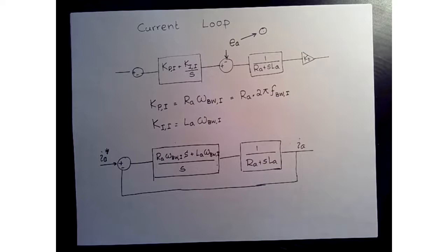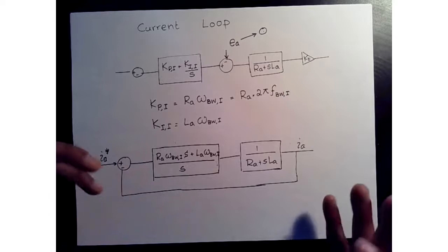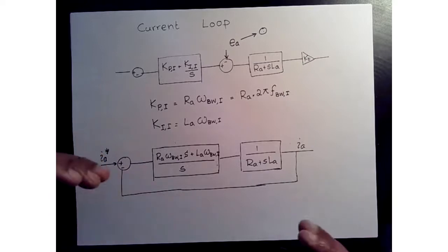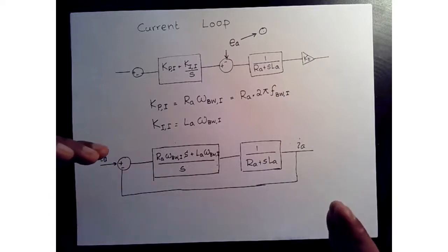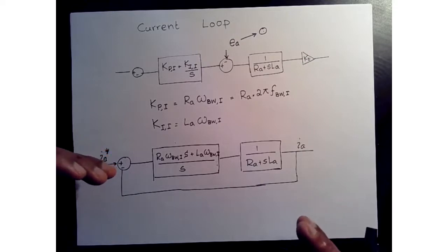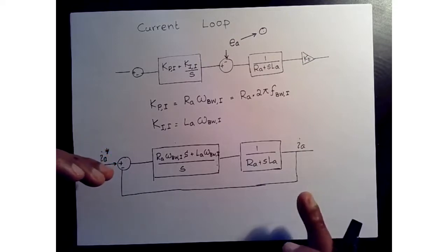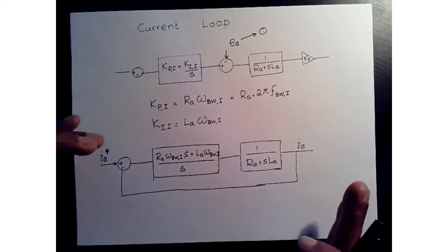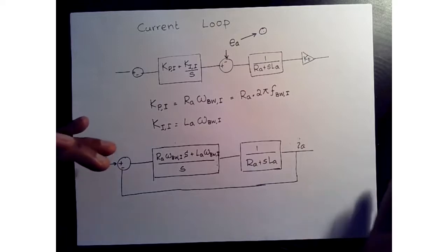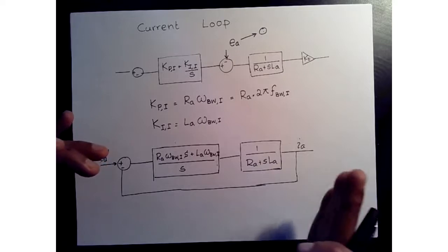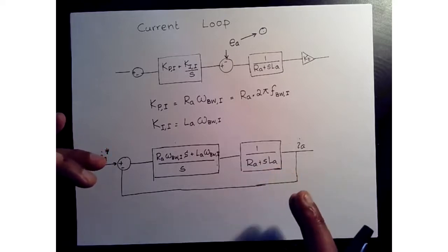Why are we focusing on controlling the bandwidth? What does bandwidth matter? Good question. Bandwidth is basically your response time. When we are designing a controller, we need to know how fast that controller is going to respond. For example, you have a torque actuator, and you can design your torque actuation to have a response in the seconds time scale, or in the milliseconds time scale.